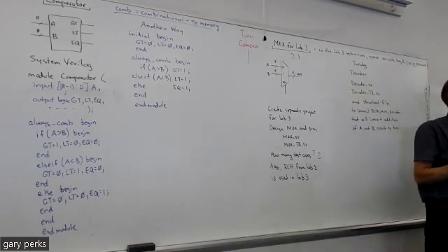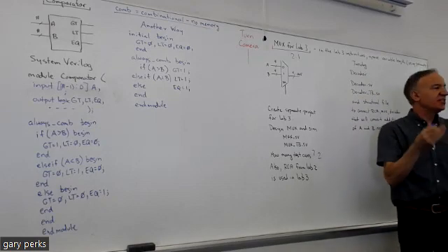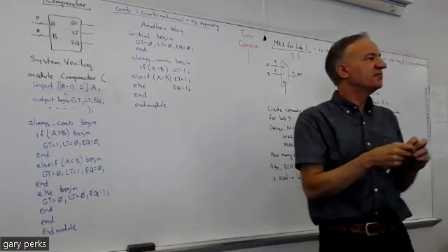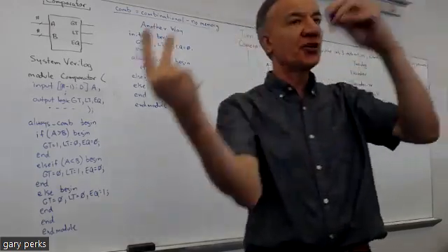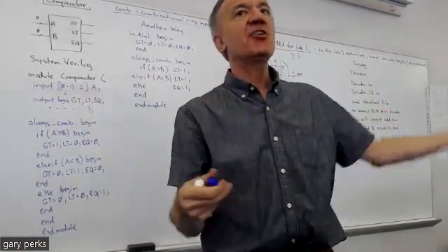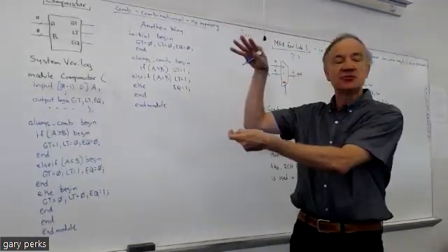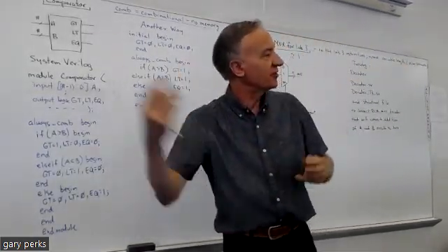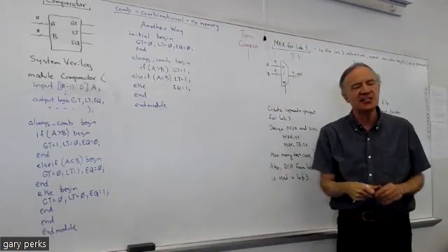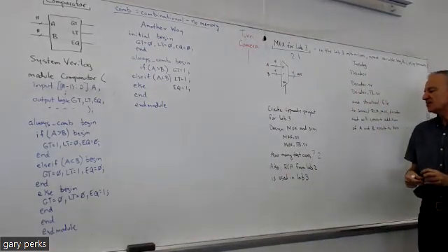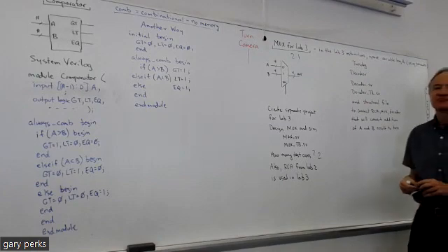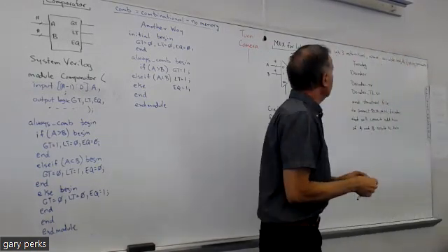We need the half adder? Yes, because the RCA is made out of the half adder and full adder. When you bring over your RCA, you got to bring over your half adder and full adder, because remember the RCA, that structural model, it basically references those. So you need them. I'm glad you actually said that out loud. That's something that people often forget.